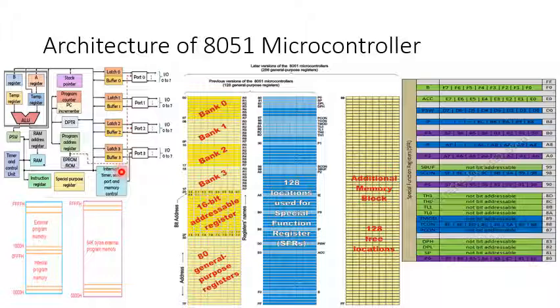The instruction register is used to decode the instruction. This register is used to decode the opcode of any instruction to be executed. After decoding, this register sends the decoded information to the timing and control unit to generate the necessary signals for the execution of the specified instruction.